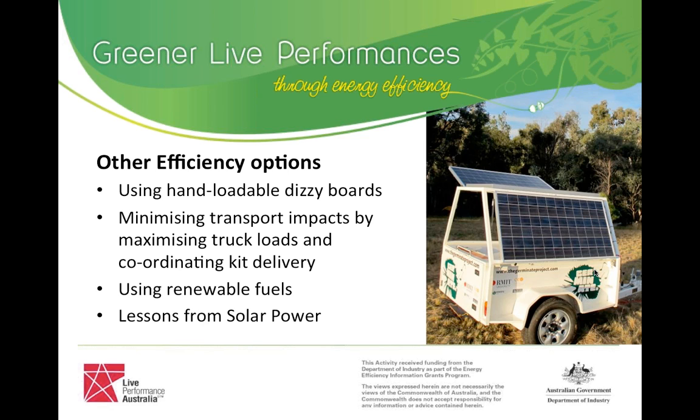What's the story there? The position on that is that the generators, as Corey mentioned earlier, generally operate at around 1500 RPM, except for those little small noisy things that you hear on some small events. Now, as load is applied to the generator, the governor of the engine says, I need more fuel to burn to meet that load demand.